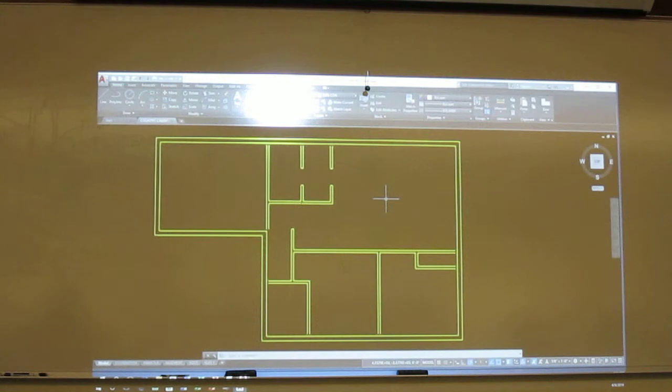There is a standard on the order of the sheets. Typically, we always place the drawings in the order that our construction crews are going to show up. So we would look at a site plan first, because we have to develop the site first. Then we would go to the foundation plan. Then we'd go to the lower floor, the next floor up, the next floor up. Then we'd go to a roof plan, because that's the way we build from the ground up. We design from the top down, we build from the bottom up. And then end with some exterior types of views.